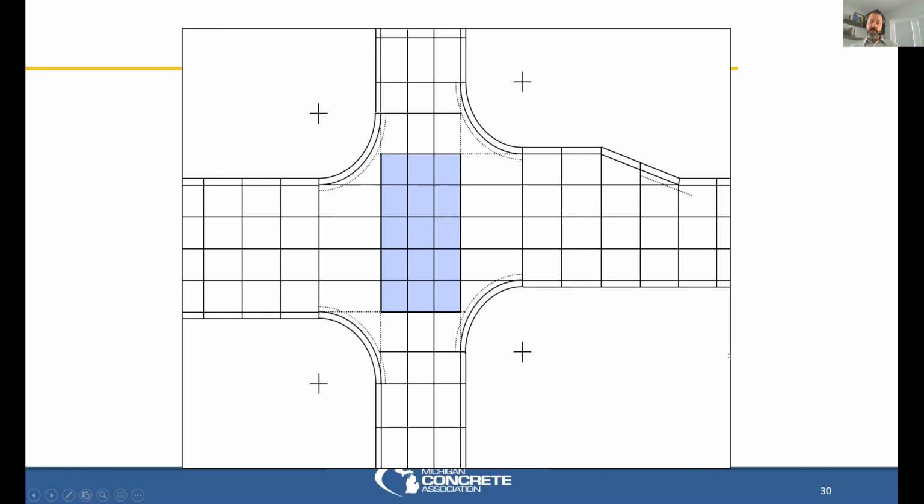No. So any of you designers out there that are doing not necessarily pavements, because we have a good handle on that, but I still see it in a lot of other specs for sidewalks, parking lots, alleyways, all these other different concrete projects where you'd be doing some flat work, and they still want to use expansion joints every 50 feet, every 100 feet, every 200 feet. And the answer to that is no, that's not necessary. Expansion joints are typically overused and over specified in those locations, and then they're typically not done right, and they cause more problems than they're actually worth.